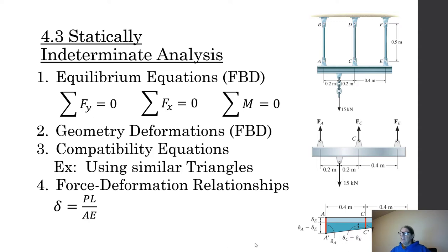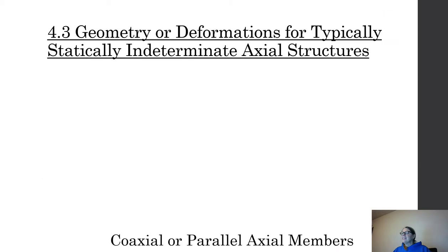And I can relate those now back into my deformation, and my unknowns are the forces that I have in my system. So I'm going to use equilibrium equations, and I'm going to use deformation to get that extra equation I need in order to find a solution. It's actually pretty cool, and then you solve the equations. So it's like, wow, we're one step closer to learning some more advanced things.